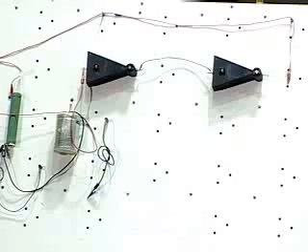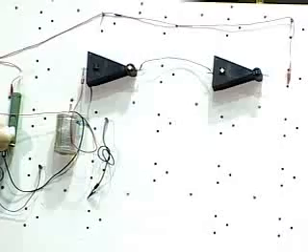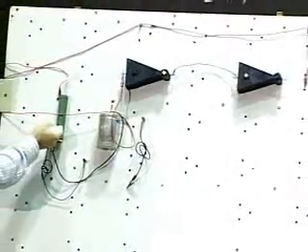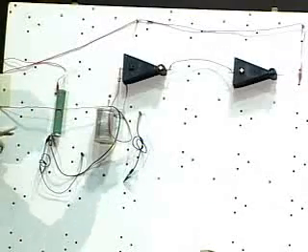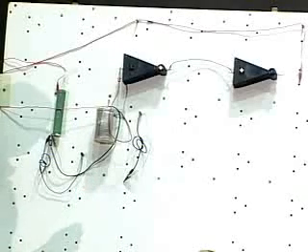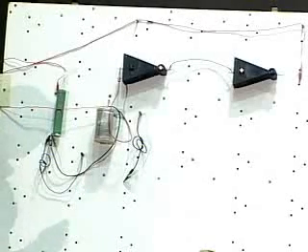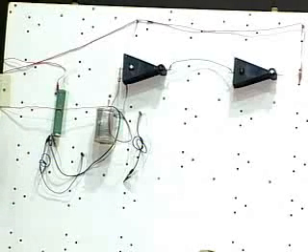Now, don't store. Okay, it lasts about a second. The elements here are 20,000 microfarads and 100 ohms, which gives me a time constant of 2 seconds. Assuming a VOC of the order of, let's say, I don't know what it is for this case, 2.5, the log would be about 0.5. So it cuts the time to about 1. So it lasts about 1 second, if my math is all correct.